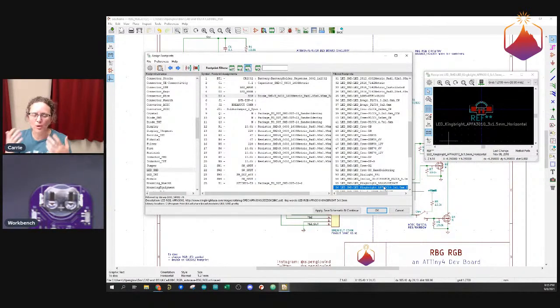On a screen, you just don't have enough context because you're always looking at everything so zoomed in, because these components are all tiny. You just don't have a good idea of what actual scale is when you're designing a circuit board on the computer. So it's always super important to print it out, take an actual component with tweezers, put it on there and check it.